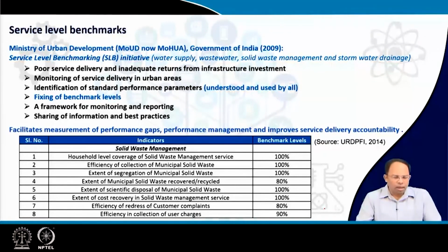For example, in this table you can see that for solid waste management, the government has given some benchmarks, such as household level coverage of solid waste management should be 100%. That means every house should be covered. So if a municipal area is covered 70%, definitely that means they have a long way to go. They have to bridge that gap of 30%. So from there also we can determine the service gap.